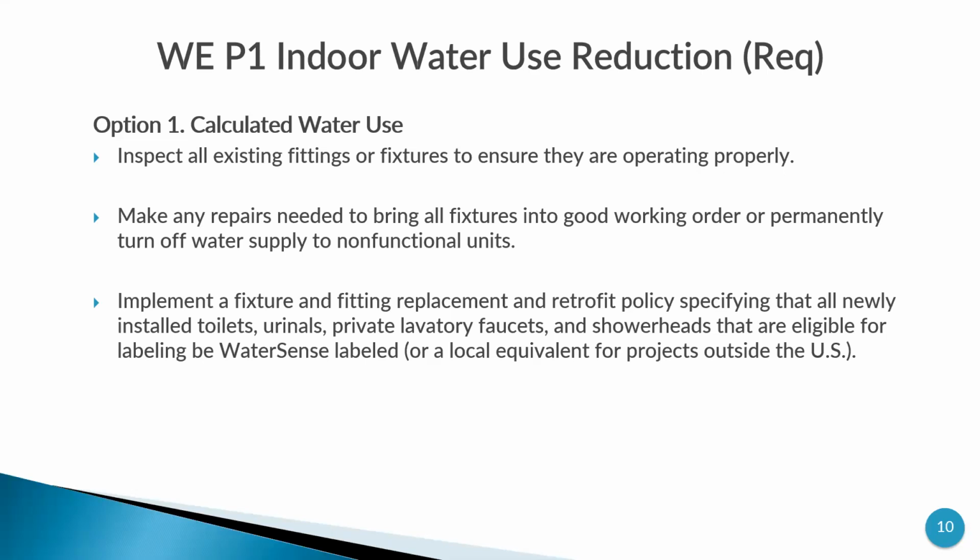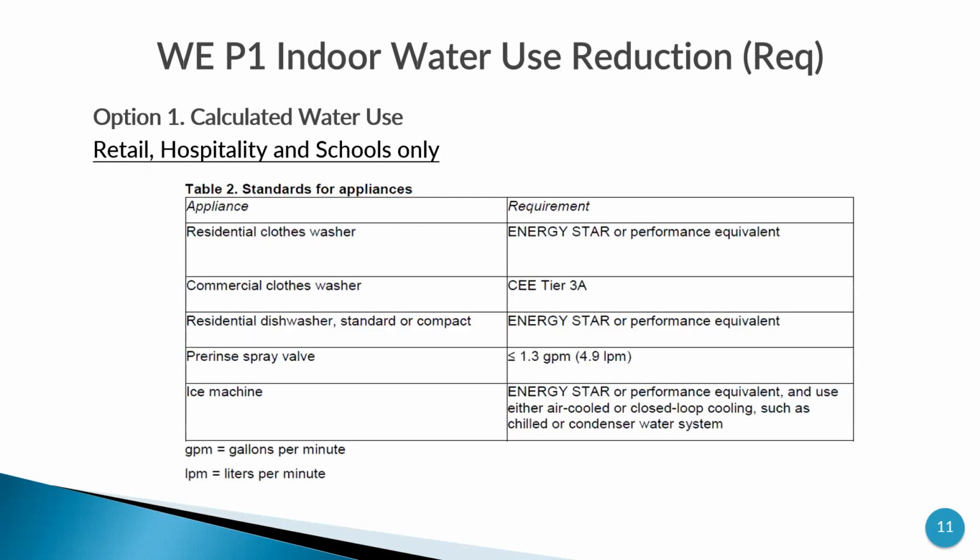Implement a fixture and fitting replacement and retrofit policy specifying that all newly installed toilets, urinals, private lavatory faucets, and showerheads that are eligible for labeling be WaterSense labeled. WaterSense labeled are those fixtures that meet the requirement, or local equivalent for projects outside the US.